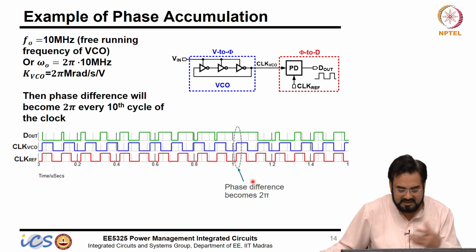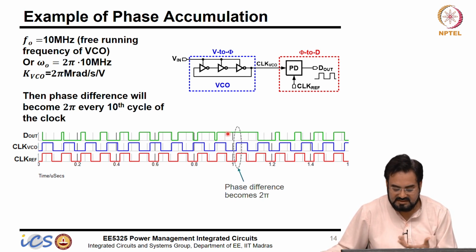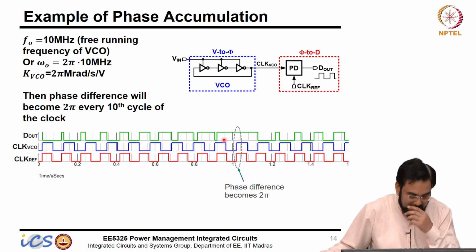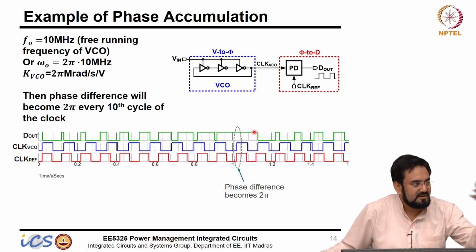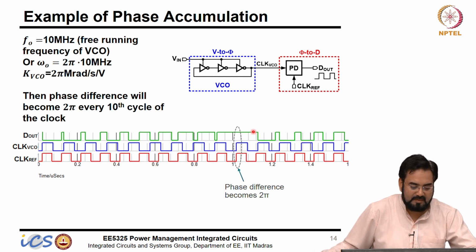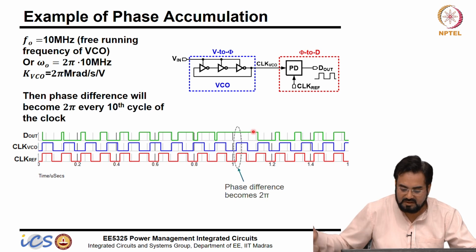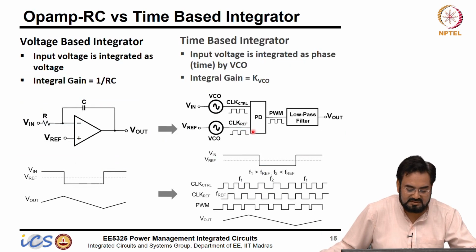And in a converter we call it duty cycle slip, because this cycle corresponds to a duty cycle here. So every 2 pi, which means your converter should settle before it goes to 2 pi, otherwise you will get a cycle slip, and at the output your regulation will go completely out of regulation. So how we fix that, we have some techniques, we will tell you later.